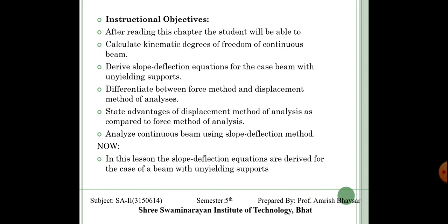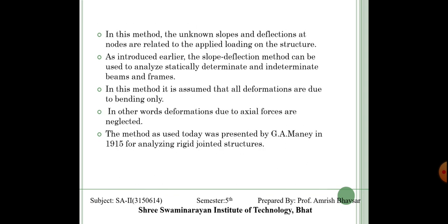So now in this lesson, the slope deflection equations are derived for the case of a beam with unyielding supports. In this method, the unknown slopes and deflections at the nodes are related to the applied load on the structure. This is most important. As introduced earlier, the slope deflection method can be used to analyze statically determinate and indeterminate beams and frames also.